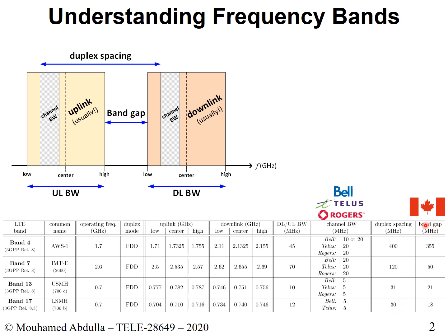The other thing that might be interesting to observe when you have FDD, right? So this chart essentially, if I were to summarize it, is an FDD chart. You have certain frequencies for downlink and certain frequencies for uplink. So the other thing that is necessary to look at when you have an FDD chart is the band gap. What is the gap between the downlink frequencies and the uplink frequencies? This thing here is the band gap. You just take this one minus this, and that gives you the value, which is here. So in this case, you take this, that's the low for the downlink. You subtract it from the high for the uplink, and that should give you this value here. Okay, so that covers all that we need for this table.